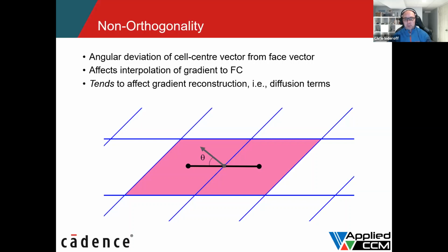And so where this is going to show up for most of us, OpenFOAM is used for a huge range of applications, incompressible and compressible, but compressible solvers will probably be where you run across it the most. It's our friend the pressure equation, which is a pressure Laplacian.